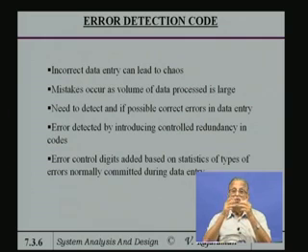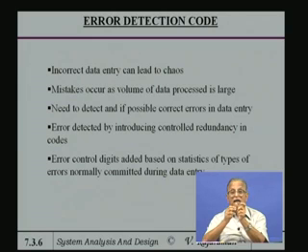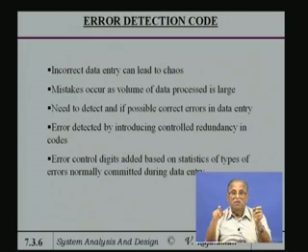Like all of you in a digital computer design course or logic course would have talked about the parity bit. To a certain number of data bits, you add a parity bit, and the total together, if the parity fails, then you say there is a single error in one of the bits, and so it is an error detecting code.